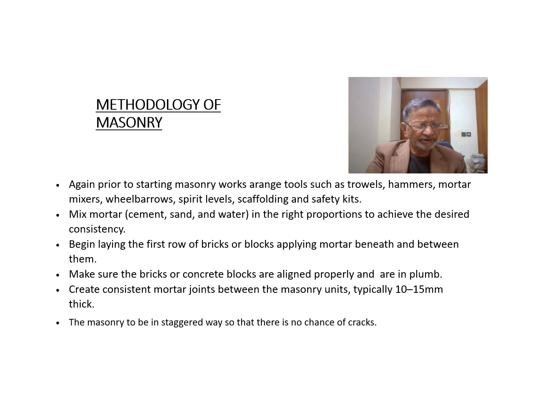Same way, to check the alignment and plumb, we have to use the plumb bob or the leveling instruments, and we have to check the alignment with the leveling instrument as well. So the joints must be in a staggered way. No joint should be one above the other, so that there should not be any chance of cracks.